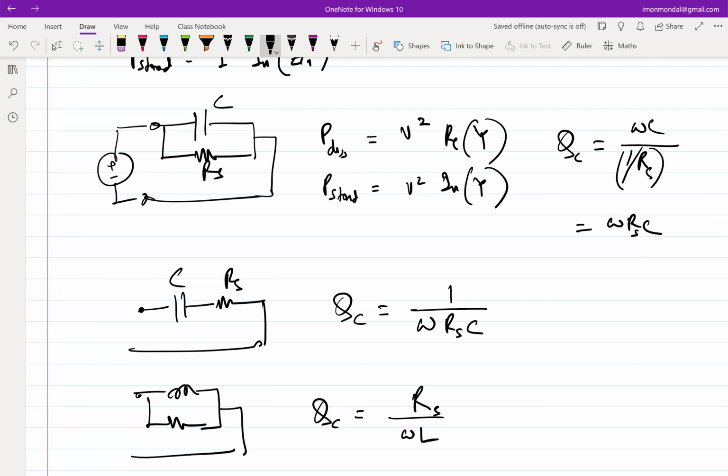put in another term? The reason we need to put in another term is that even though it gives you the feel that everything is very controllable in the denominator, omega RC, it's not, because omega is fixed, set by the system. Then you might say that R and C I can choose, or R and L I can choose. L you can choose, but the R comes with the L. Right? Ideally, I want the R to be 0. I want a lossless element. Right?